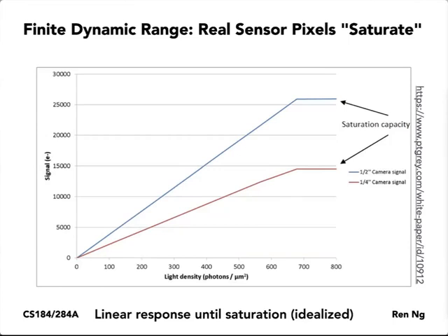And then you get a saturated value, which is after that light intensity. At brighter intensities, nothing happens to change the pixel value. It's saturated, okay? The pixel can't hold any more electrons. It's maxed out, all right?